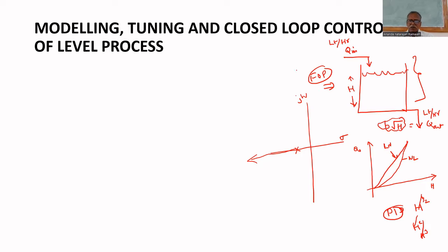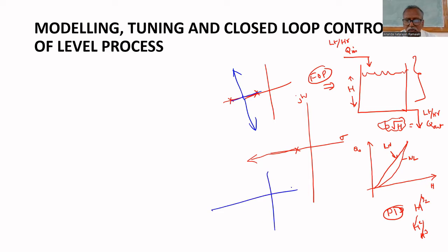Similarly, consider the root locus of a stable second order system. It will be like this. If you select any point here, to its right there is an odd number of poles, so this is part of the root locus. Then it breaks away and goes like this. It never crosses the j omega axis. But if you take a third order system, it breaks away, goes to infinity, and comes this way. So as we increase k, after some point it becomes unstable.